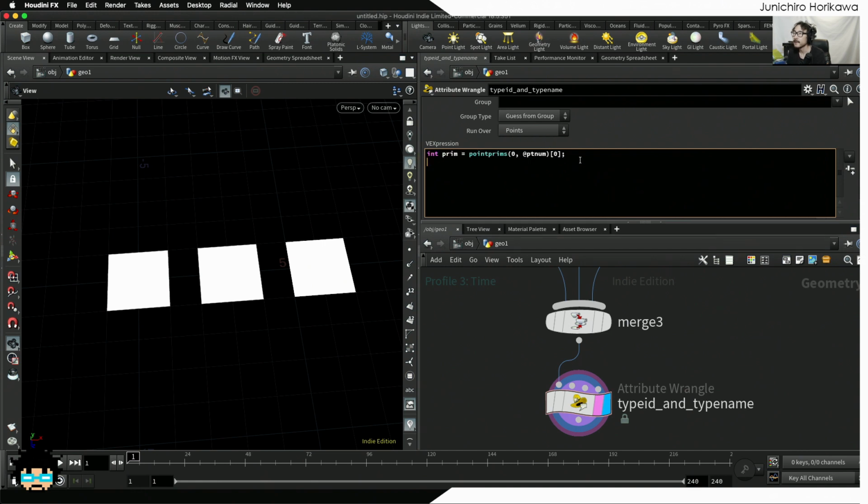From this primitive number, I'm going to retrieve the type ID from the primitive intrinsic attributes using the primintrinsic function. So int typeid = primintrinsic(0, "typeid", prim). This should give you a type ID for each primitive, for each point.